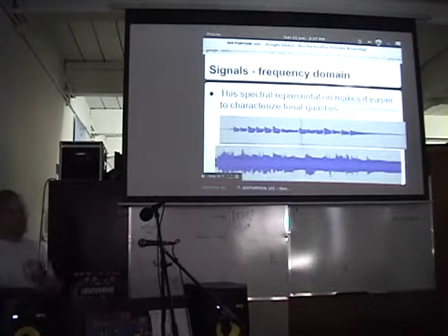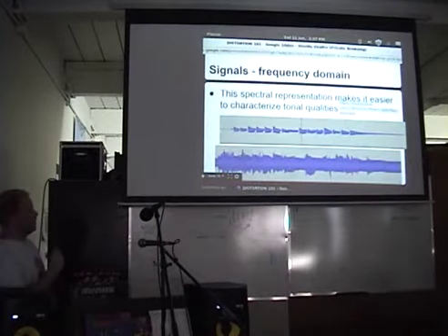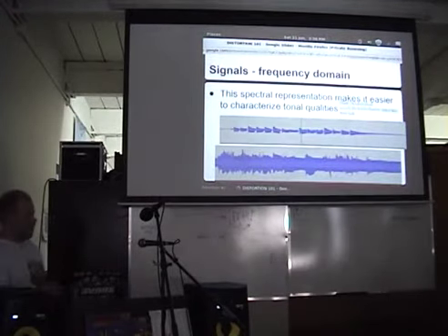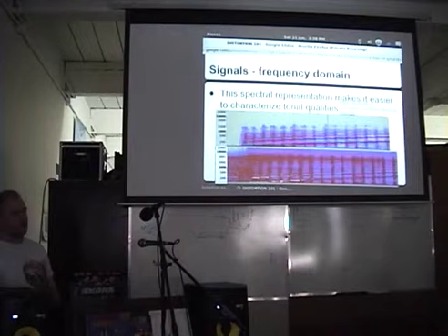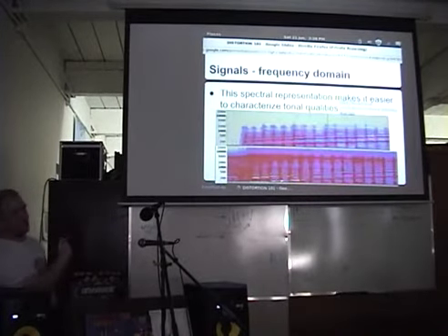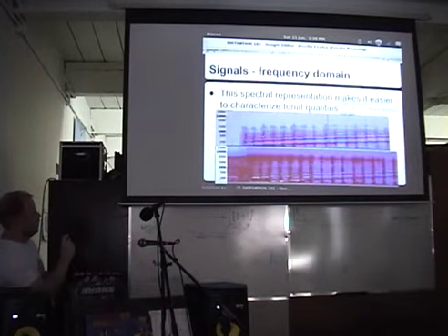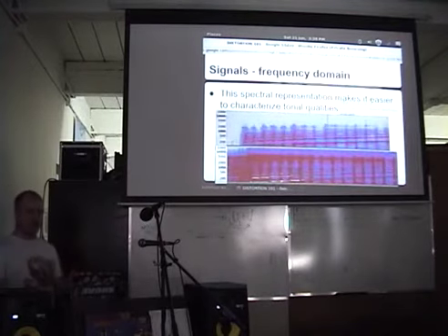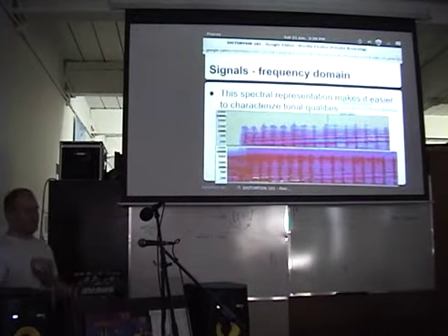So how do you glean that from this time domain signal? You can see everything looks smattered out and it's just a big mess. But if you take a look at a spectrogram, you can see this is the original and the distorted signal. You can see our original content is reproduced here, but there's all this high frequency stuff that's changing the actual tonality of the signal, and that's where you hear these differences.